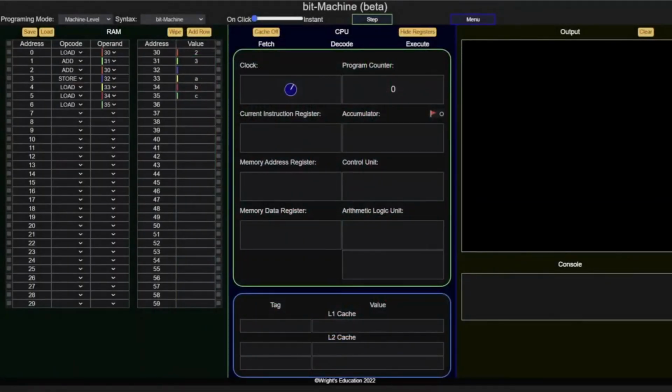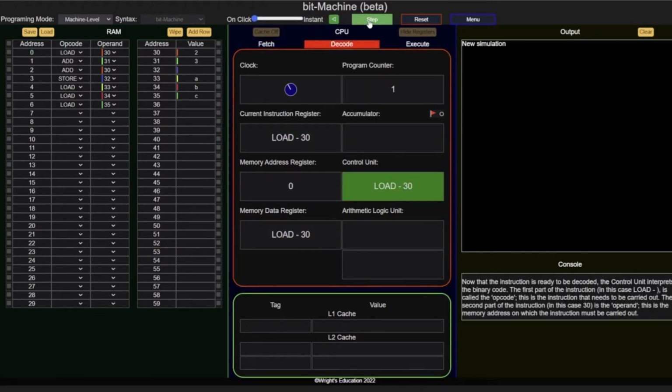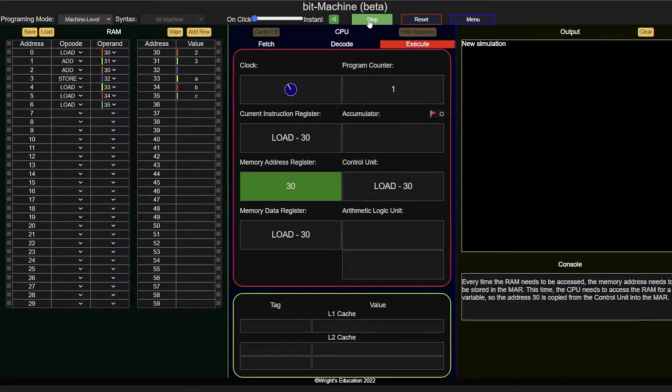Entering the program instructions of the SAP1 emulator: when a program is executed, the program counter will start at 0 and load the first instruction from the memory address. As the program cycles through RAM addresses 1, 2, and 3, and so on, until the program reaches a halt or until reaching address 15, after which the program will wrap around and continue to run from 0.